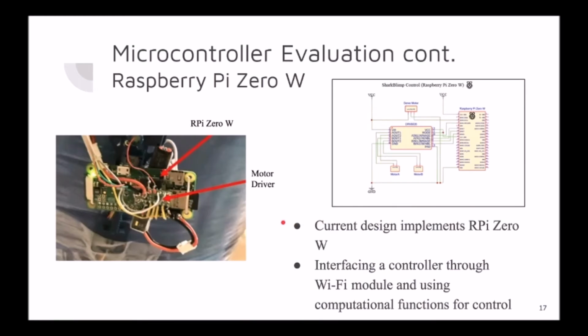For our Raspberry Pi based blimps, we decided on a direct soldering method by using some jumper wires and interfacing the controller through the Wi-Fi module, as well as using the computer keys for the commands. Here we can see what it looks like when mounted on one of our blimps and a simple schematic showing the connections.